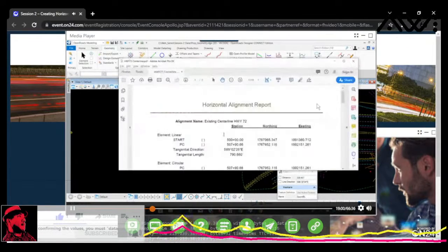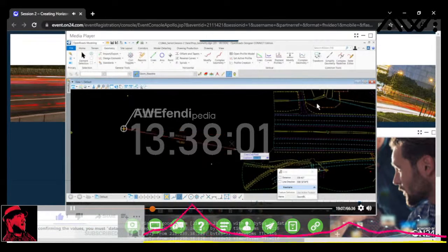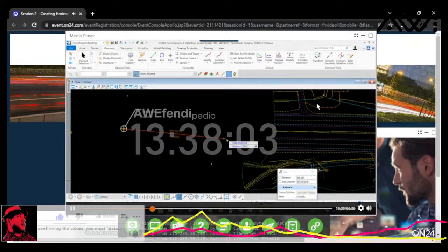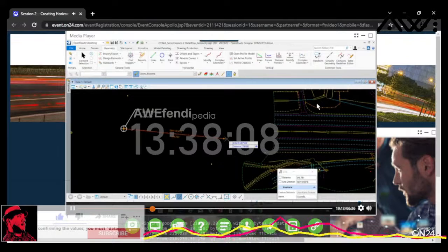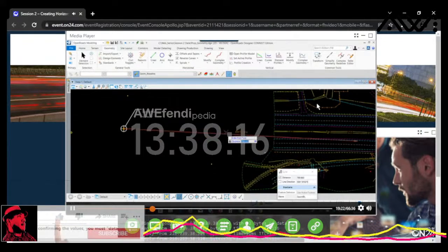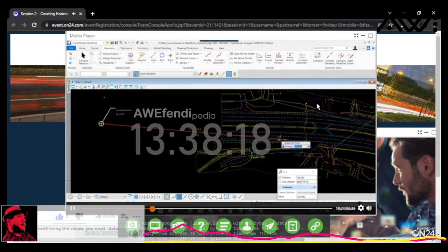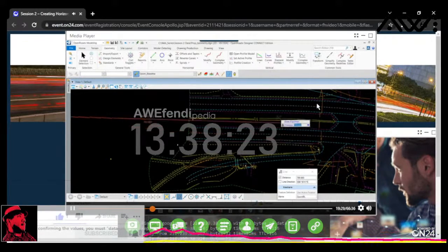Since, again, this is what I'm adhering to, I'll see that first distance is 790.66. So I'll key that in. I'll click the Tab key or the Enter key. And this is the interaction part with that dialog, okay? To hold that value, I'll type it in and click the Tab key. Now that locks that value in place, meaning I have a fixed 790-foot segment. The bearing is still free so that I can move that in any direction I want, but the distance is locked.